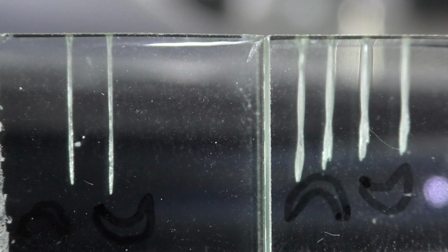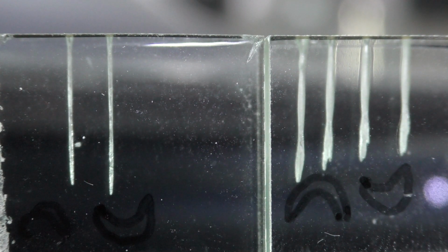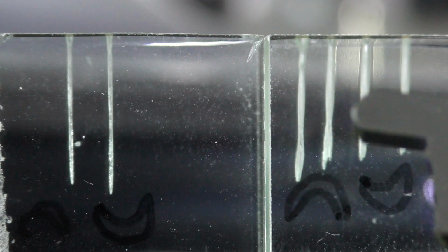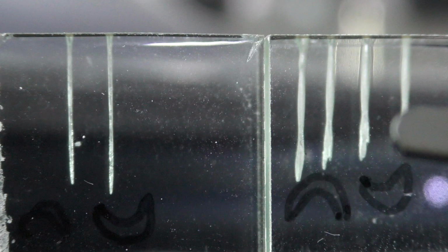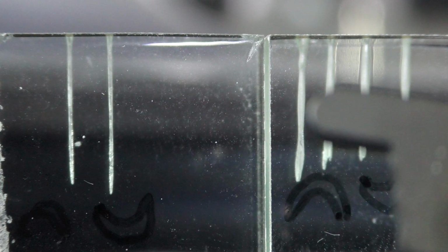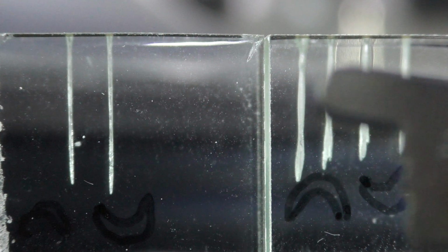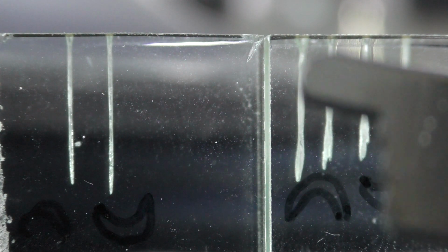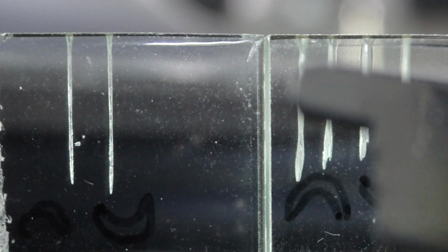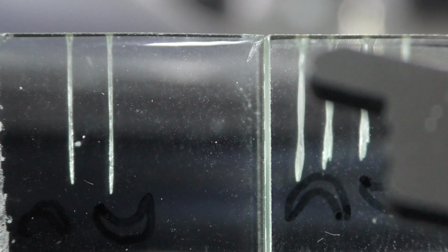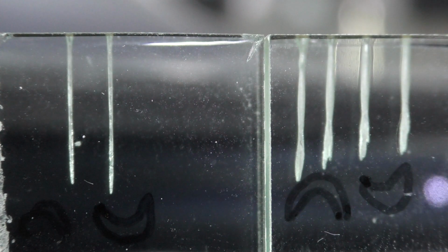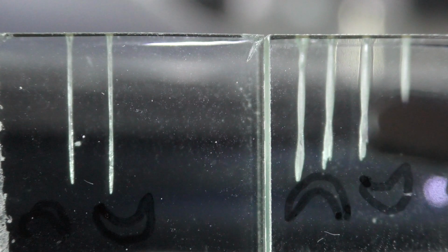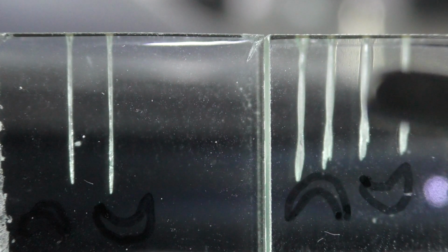So when I do a penetration test between the two machines, I don't think there's any doubt in your mind which machine is which. These here are from the standard 8mm beam, my 70-watt machine. Now, these are the two compound lenses, and I changed the focal distance between these two because it looked as though just here there was a neck which indicated that my focal distance was a bit low and I really ought to raise it up. And as I raised it up, so I got rid of this neck and made the thinnest point onto the surface. And then I did much the same sort of thing with the other lens combination. I tested that at both focus depths.